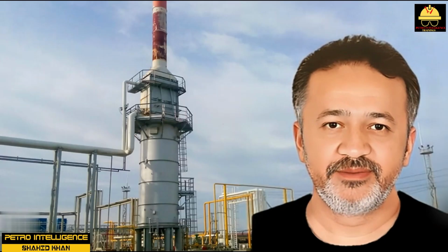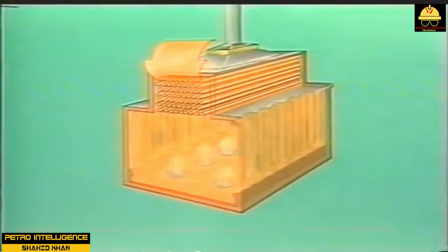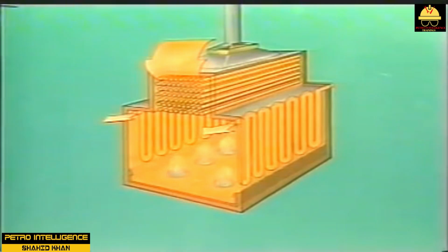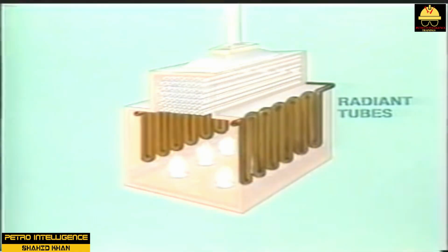Heat transfer. The primary means of heat transfer in a fired heater are radiant heat transfer and convection. However, heat must pass through the walls by conduction to be absorbed by the flowing fluid. In the fired furnace, the flame on the burner is the radiant heat source. Radiant heat transfer takes place primarily in the firebox. Tubes located in the firebox are referred to as radiant coils or tubes. The tubes transfer heat to the fluid by conduction.